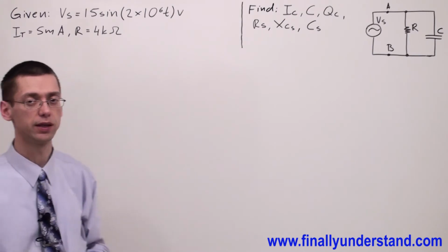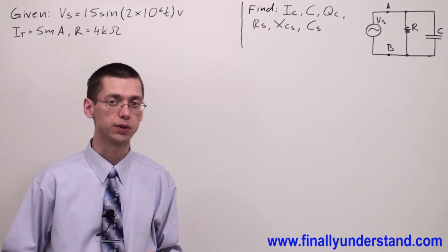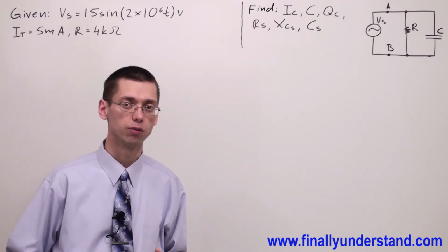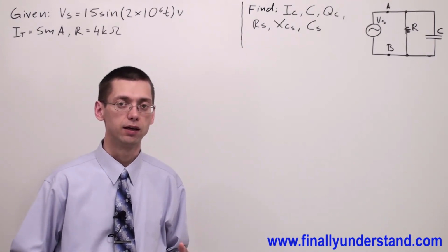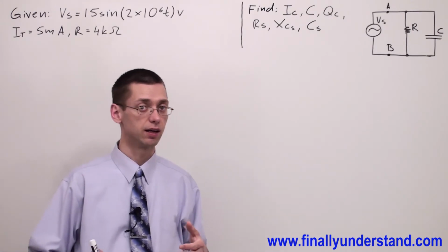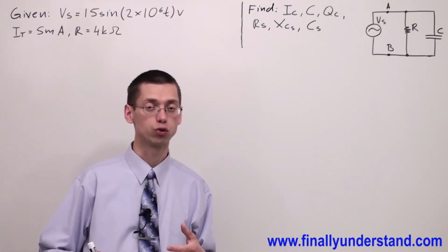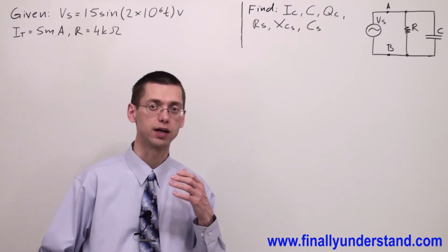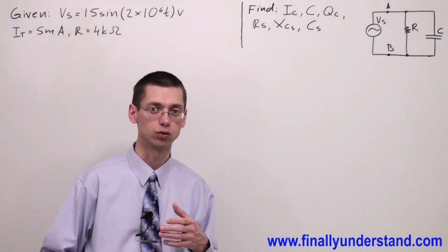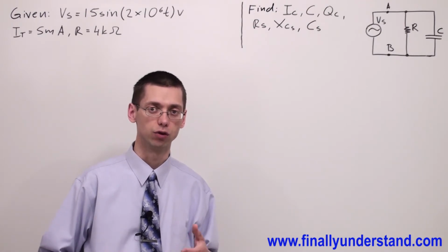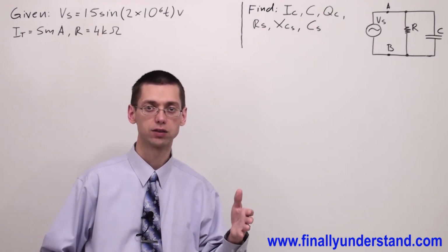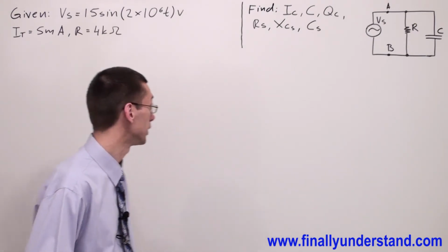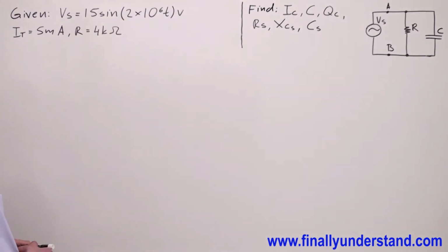given is also peak. If it's going to be specified different, you are going to use RMS values or peak values. What I mean by that, if let's say voltage peak is given and RMS current is given, you're supposed to convert RMS to peak or peak to RMS. You cannot mix RMS with peak, okay? So you're supposed to use one type of the voltage or current. If RMS voltage is given, you're supposed to deal with RMS current. And if voltage peak is given, you're supposed to deal with current peak.